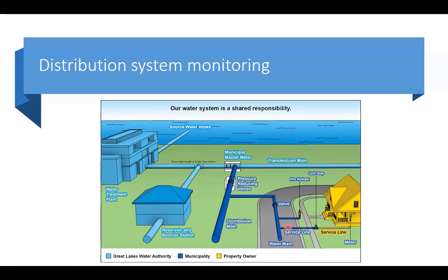Typically, the service line is essentially divided in half with a curb stop in the middle. The curb stop, you can find that typically with a breastplate, and that is where water can be shut off to a residence. The area on the street side of that curb stop is typically referred to as the public side. So this is owned by the utility.